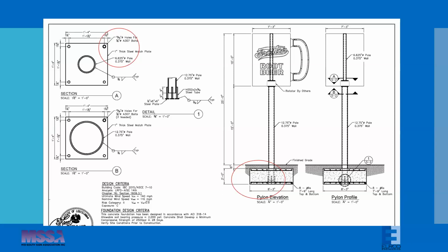That metal to soil interface creates corrosion. There's the electropotential difference between metal and soil that causes corrosion. And so by having those feet, it does 2 things. One is it gets the pole up off the bottom of the foundation so that you don't have that soil interface. But secondly, and equally important, as you're pouring the concrete in the foundation, it allows the concrete to flow up into the base of the pipe. And it really helps to lock the pole in place so that it won't wiggle or wobble or go anywhere.